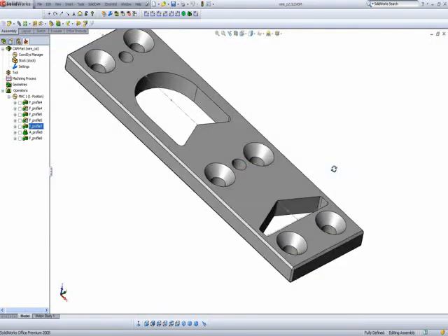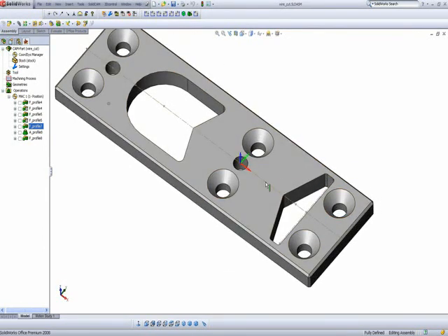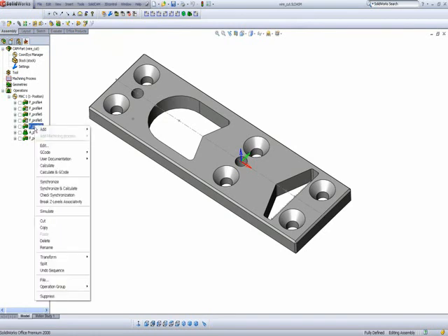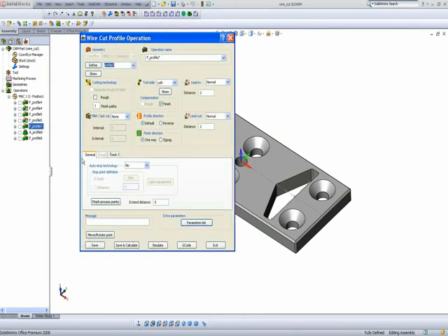In my next operation, I'd like to do these holes over here. In this case, I will be going through the very end of the part, not using the later option. If I open up my operation, you'll see I have finish path as 1, working on the left hand side. Auto stop technology, I pick none, I do not want any. Very simple operation. Finish direction only one way because I'm only doing one cut in any case. And basically we're all set.